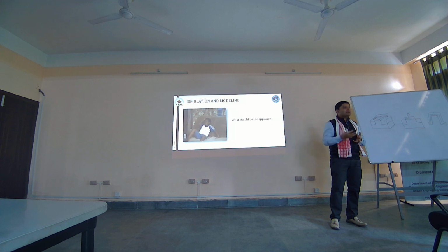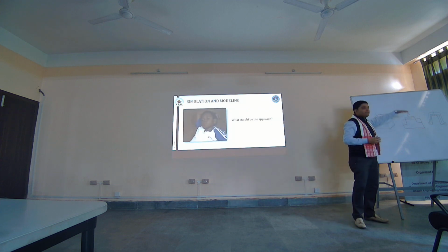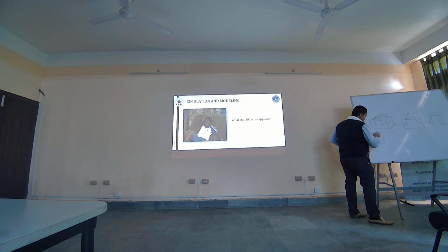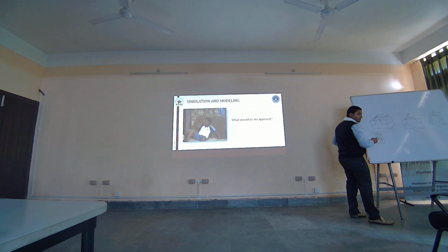So that is where these ribbon-fed architectures come into existence. And what are these ribbon-fed architectures? They are going to stack these fins on top of one another. So basically it is going to look something like this. Here is one fin which will come out. Here will be a second fin which is going to come out, right? And this is your entire gate. So this is, you can say, the front view, right?